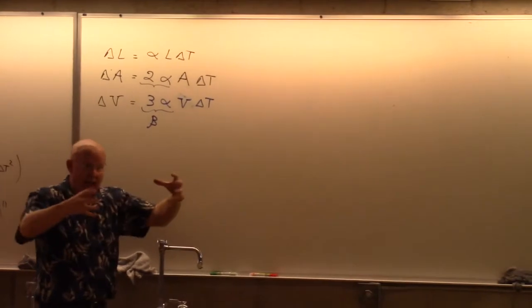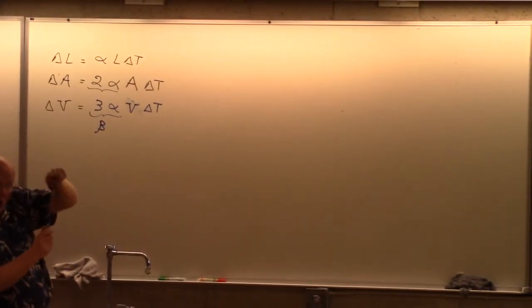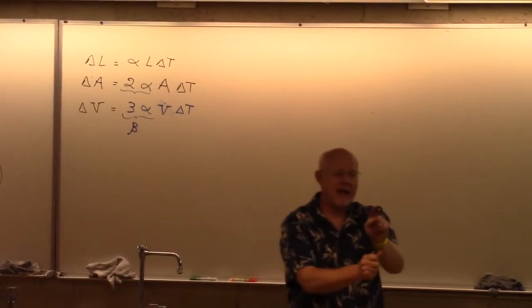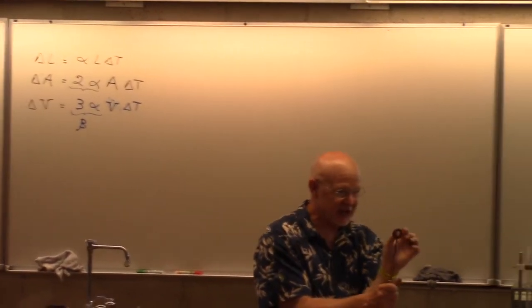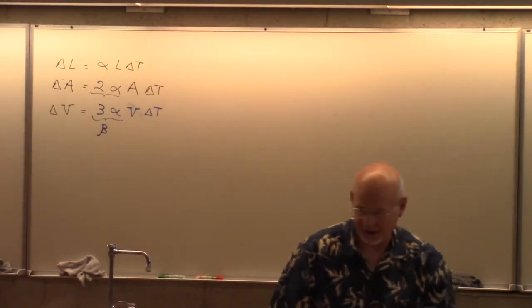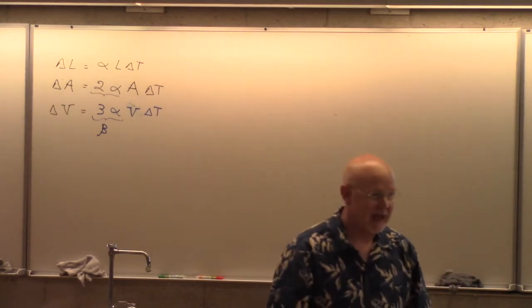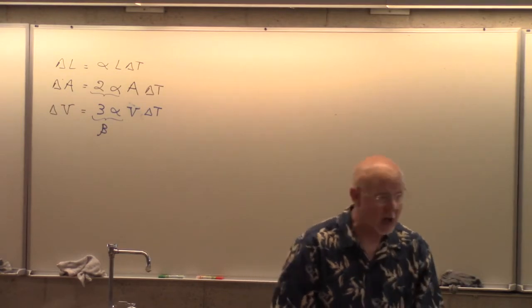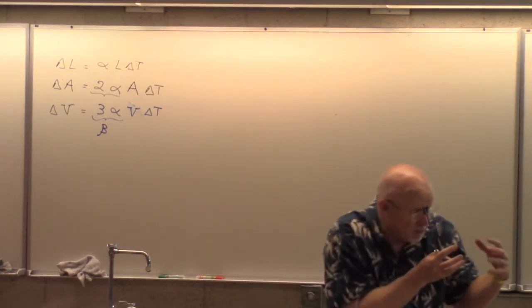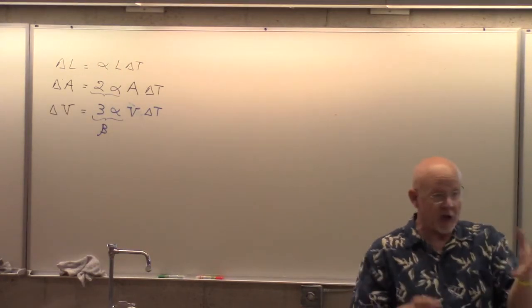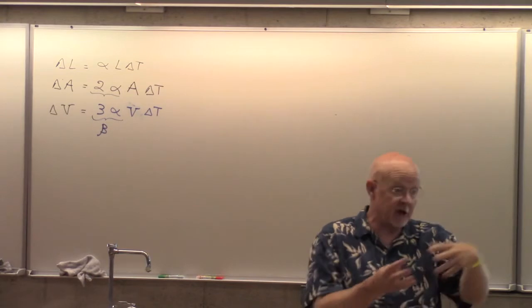If somebody were to ask me, how much does the diameter of the hole grow, I will think of it as being made out of brass and asking the question, how much does the brass in the hole grow? Even though it's a hole, it's not made out of brass. And that's the trick I want to point out here. Those are the two things I wanted to emphasize: when you are asked to calculate how much bigger a hole gets, first of all, notice it gets bigger when you warm it. And second of all, when you go to calculate it, just pretend there's material in there.